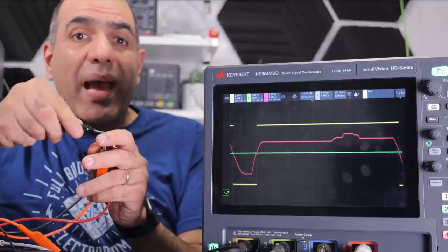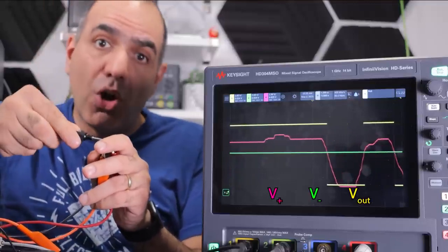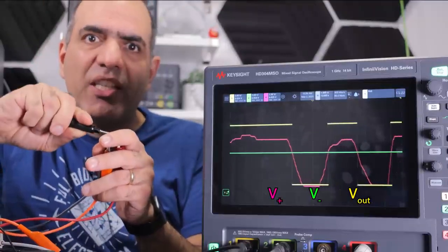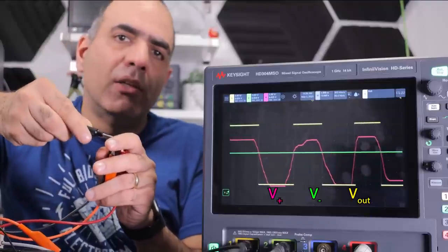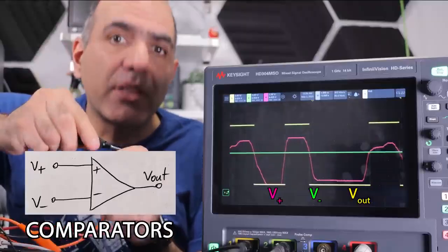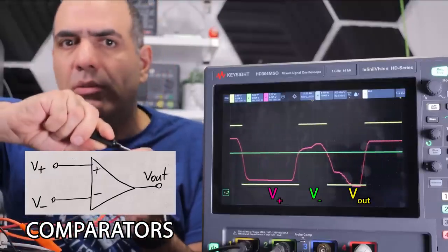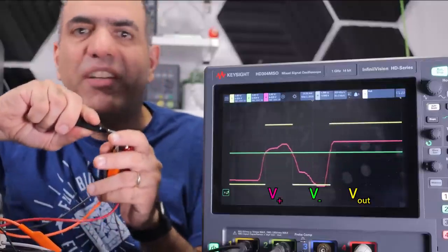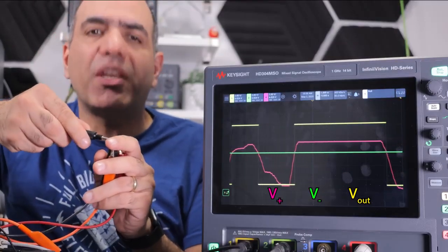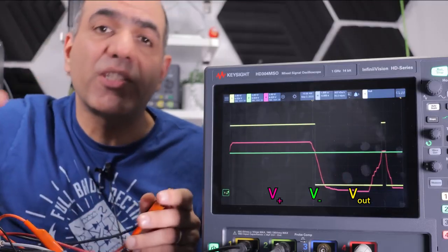So with the single op-amp, we are just comparing the 2 inputs and our output is high or low like a digital circuit based on which input is higher. If we aim to compare only, there are comparators with the same symbol that perform better than op-amps to create a digital output. Op-amps are designed to perform better in an analog circuit, although you can use them as a comparator as we see here. I'll talk about comparators in another video.